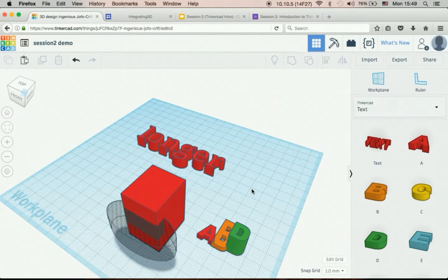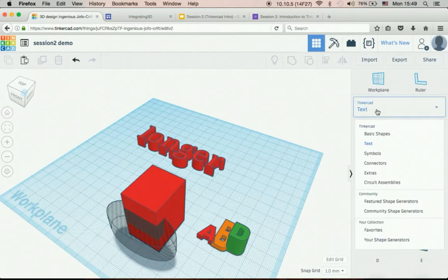So those are the very basic introduction to Tinkercad, and really the tip now is to play with it. Using those simple tools like grouping and using the combination of solids and holes, you can build a more complex geometry.